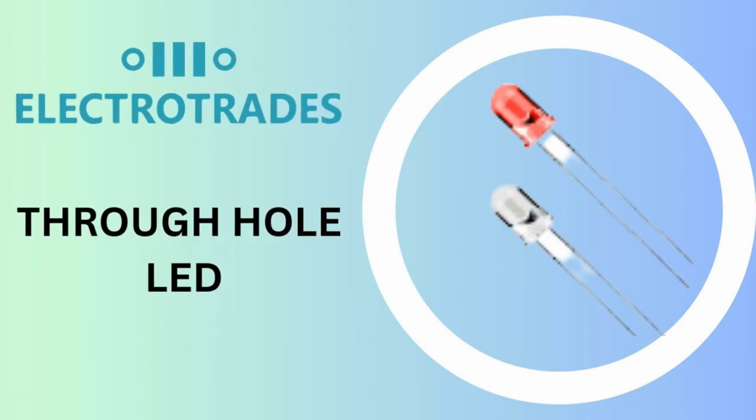Forward bias. When a positive voltage is applied to the P-type region and a negative voltage to the N-type region, i.e., the positive terminal of a power supply is connected to the P side, and the negative terminal to the N side, the potential barrier decreases, allowing the flow of current across the junction. This is called forward bias, and the diode becomes conductive.